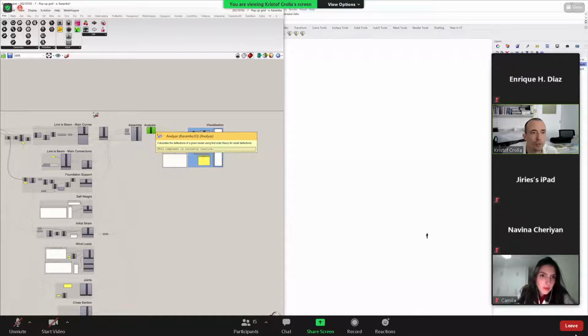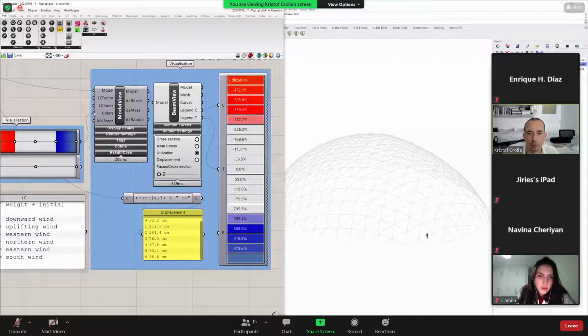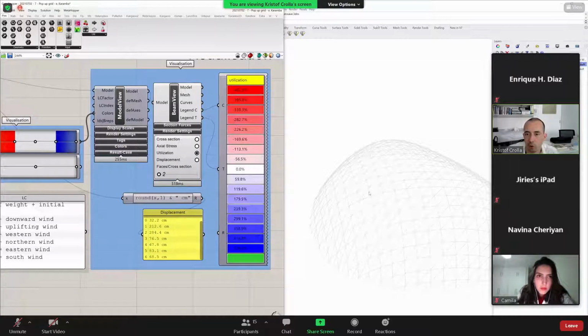Right now I'm using an absolute visualizer. If I use a relative visualizer, you'll see that I'm currently getting my extreme strains in some areas where my geometry is wrong, rather than in the areas where my actual structural analysis would matter.